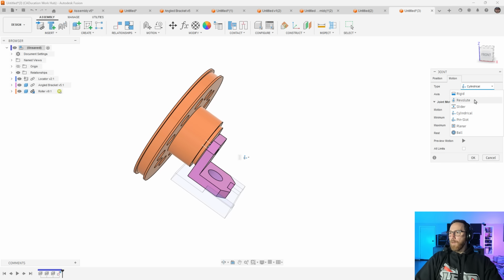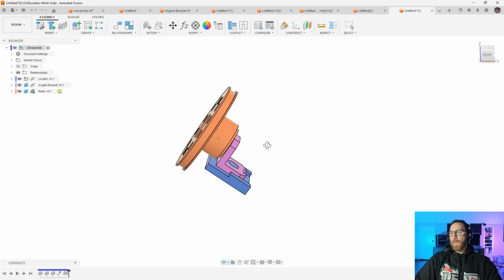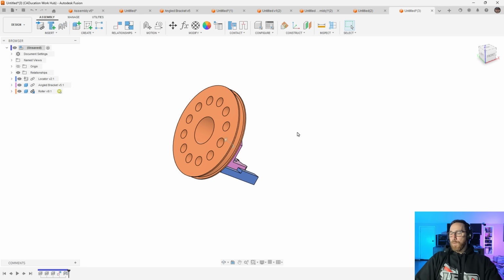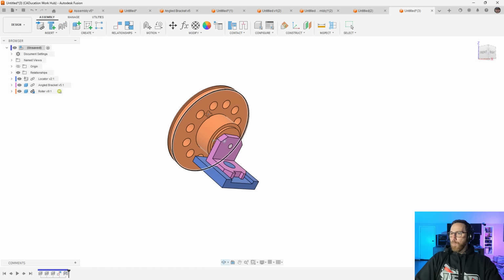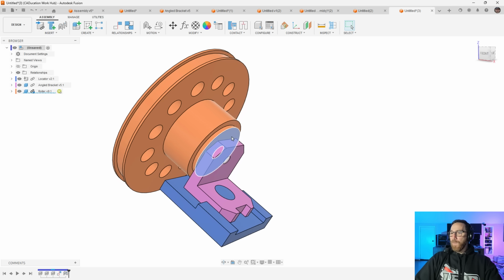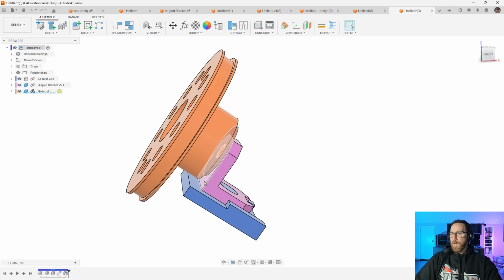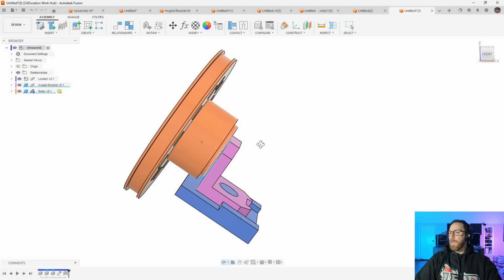And so when we think about this method of attachment, essentially what we're doing is saying we know this is how these two components move. We're going to just restrict the degrees of freedom to only allowing this to rotate. Now, in reality, what you would have is the back face of this is going to be touching the front face of this in some instances, right?